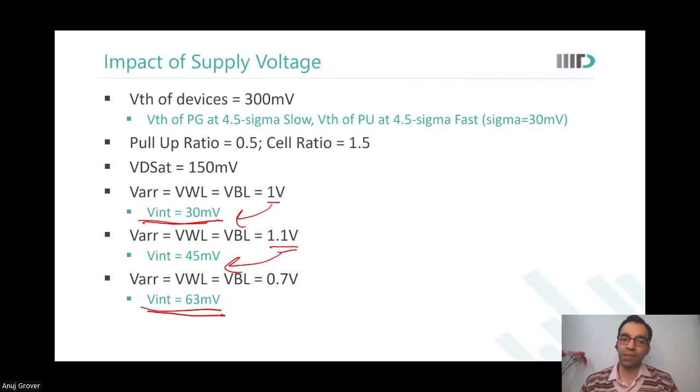Okay. So I'm not able to get it that with increase also I'm degrading, with decrease also I'm degrading. Yes, that's the challenge of a non-CMOS ratioed kind of a design. You could experience that. So there is a sweet spot. When I'm saying the supply voltage, I mean the supply for all the word line and bit line, everything. Here, though my pull-up will become weaker, the reduction in the pass gate is more, and is dominating here.